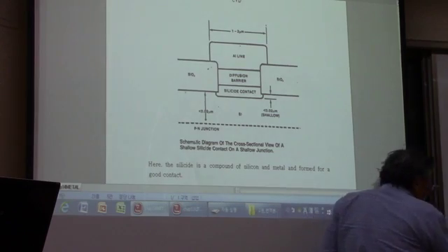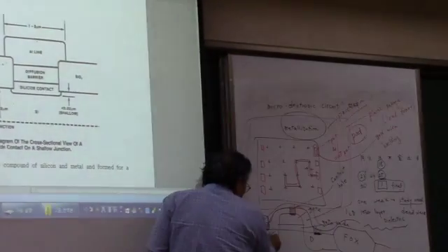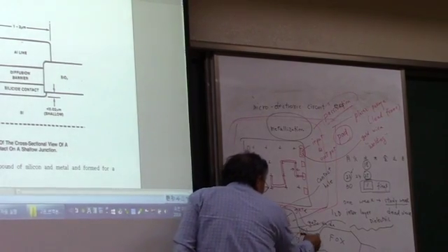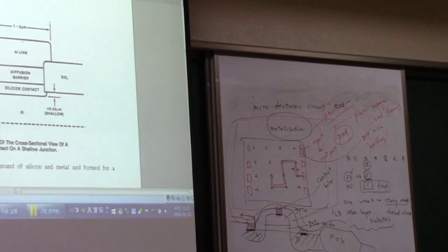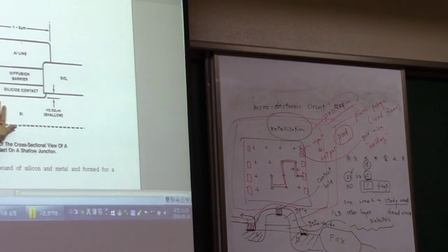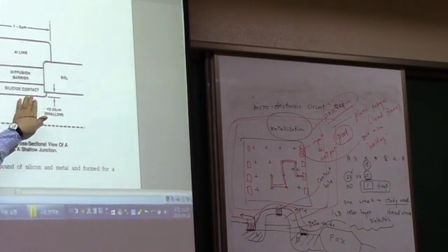So the portions that we are talking about is here and here. This is the source and drains, and you make holes on top of source and drains. And source and drains is a heavily doped area. So this silicon is a heavily doped region, and then we have a silicide contact.